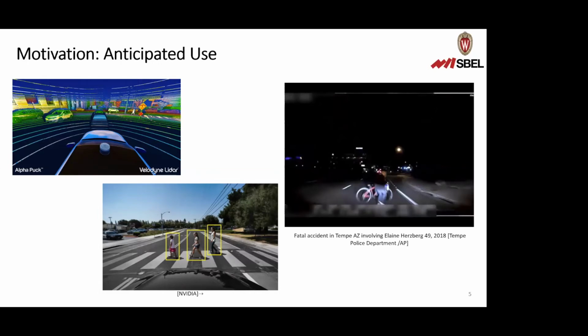One of the issues with AVs, or particularly training perception for AVs, is that if you just run in reality, you can get biases in the data that you use for training. One of those biases can actually just be children, because you don't see as many children as you do adults, so you could actually end up accidentally biasing your perception algorithm toward detecting adults at a higher success rate than children.